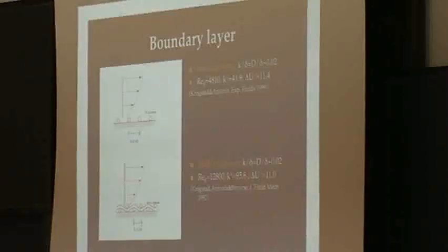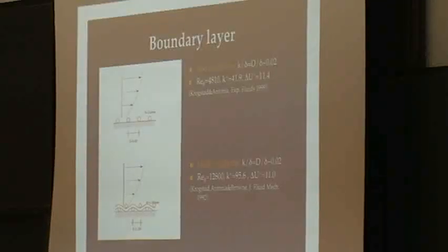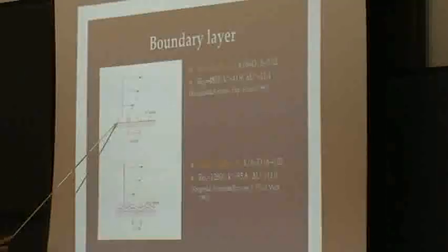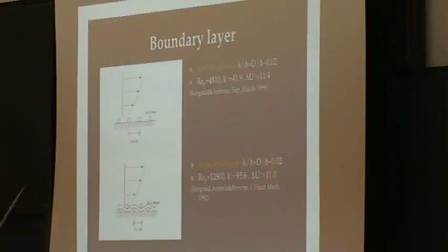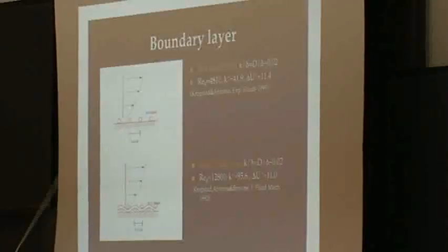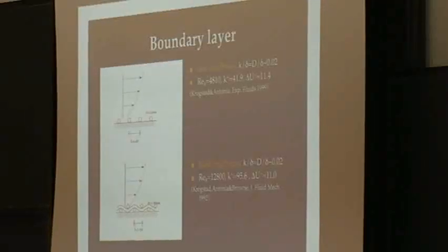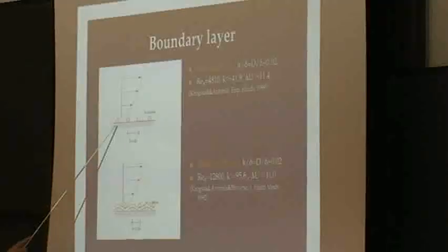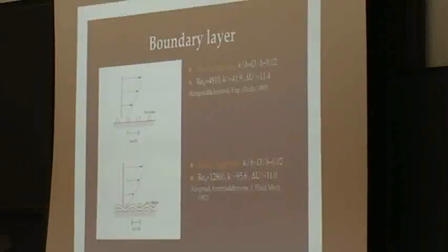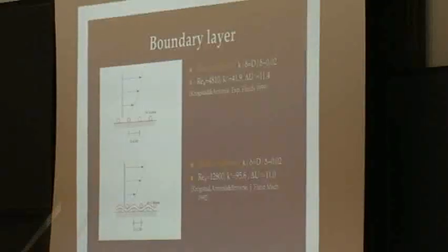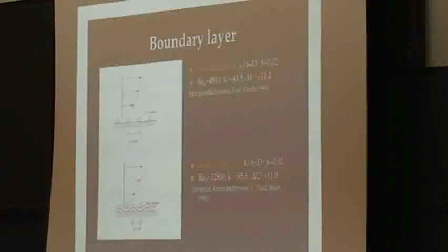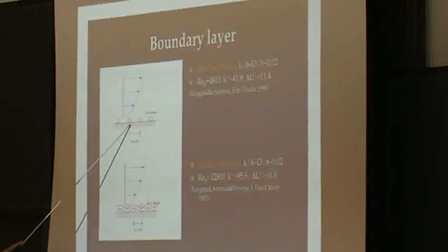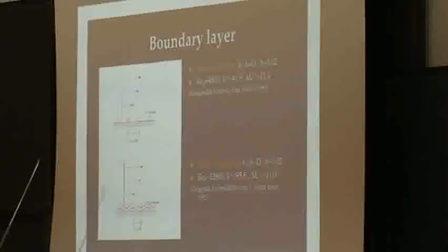The idea of doing that was that we had seen from previous studies that if you use span-wise bars, you can get a roughness effect which is very, very large if you tune the diameter to the pitch of the roughness elements. And then the idea was that if you tune this so that you get the maximum roughness effect on the flow, and you let this continue for a very long distance, when you feed information at a particular wave number into the flow, maybe some of that information survives and extends out into the